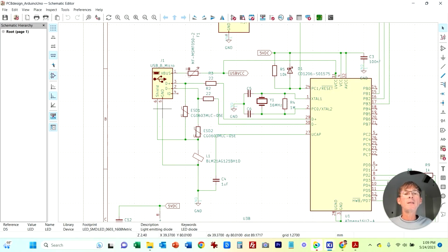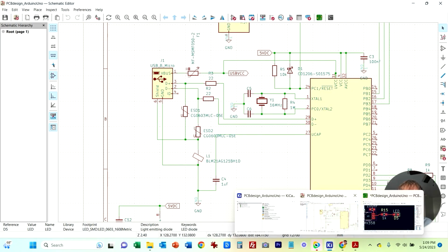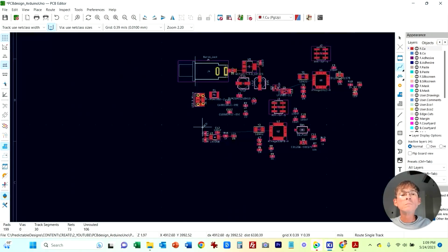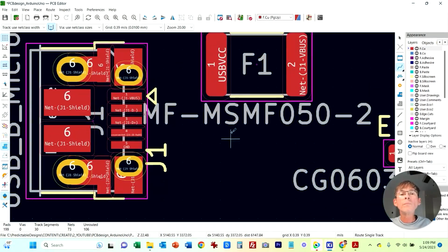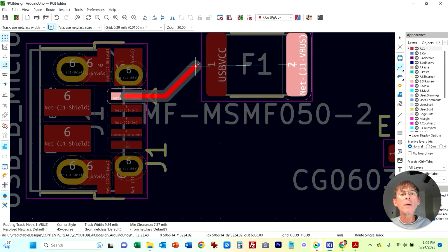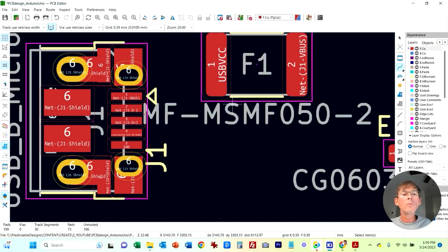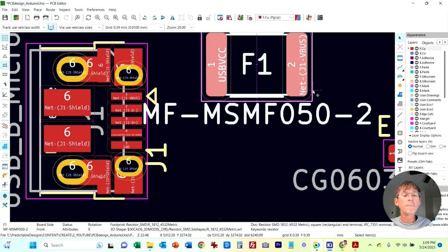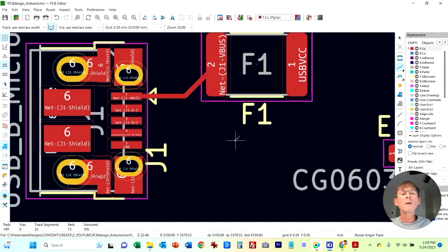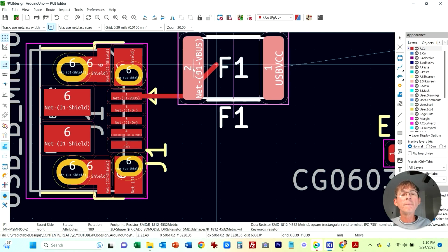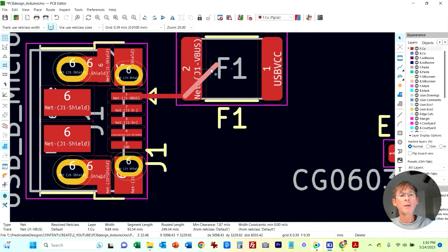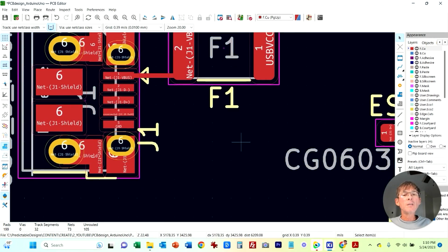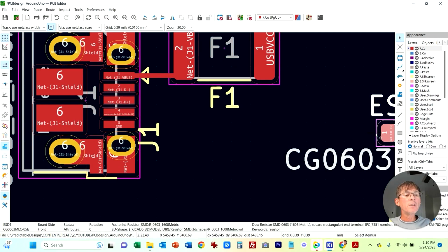Now let's maybe go ahead and start on the USB connector. Okay, it's going to first come from, here's the power, and we're going to, whoops, I've got to rotate that guy around. Let's just do it like that, with that little branch. Okay, and then we have our D lines, so this is where we need our ESD protection.